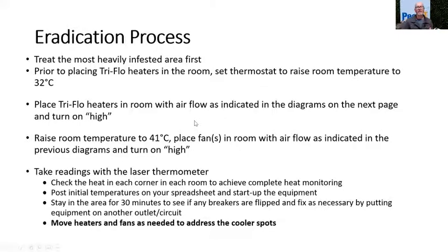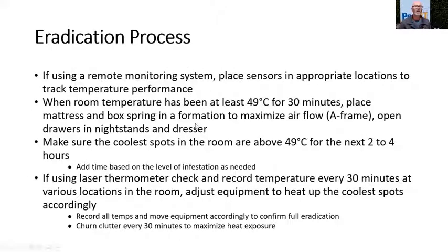Once I've reached my temperature of about 50 degrees, I'd like to hold that room for between 2 and 4 hours. If I can hold it for 2 to 4 hours, then I'm going to have a lethal treatment process in place, as long as there are no cold spots and so on. You would do some work within the room to ensure that you've removed all the cold spots.